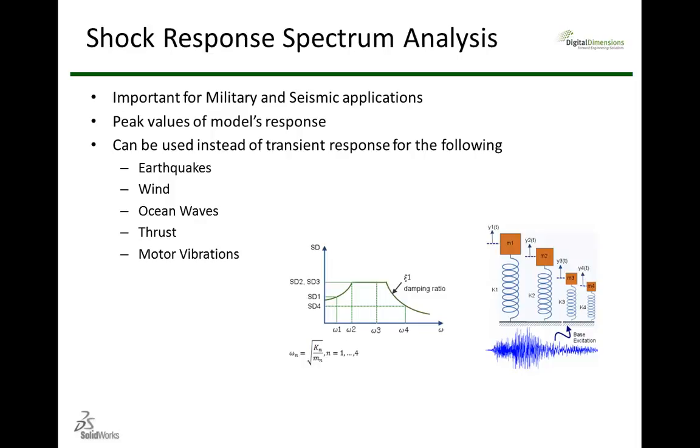So anytime you're looking at shock conditions or you want to simulate shock conditions, there are two different ways. You can either do that with a shock time history, which is what we just did in the previous simulation, or you can transfer everything into the frequency domain and do a shock response spectrum, where your load curve is actually going to be in the frequency domain, and it's going to simulate the maximum response or the maximum input load that your structure is going to see.